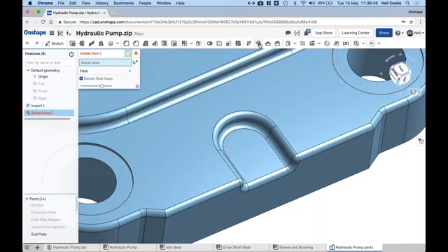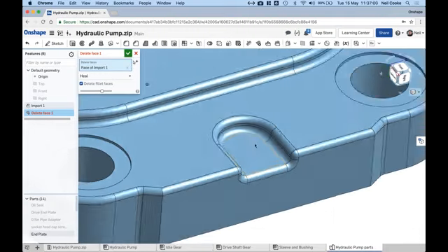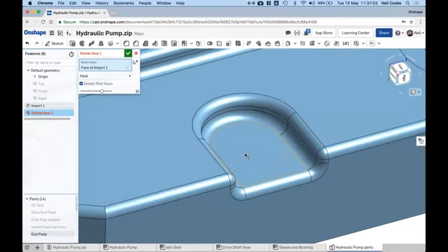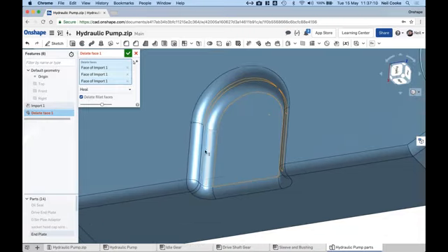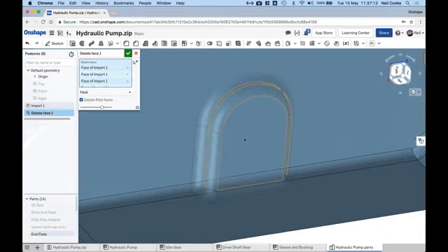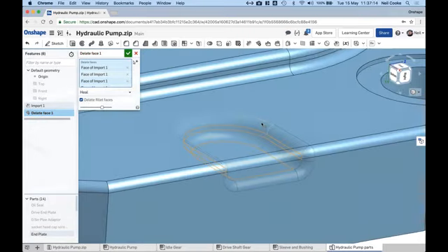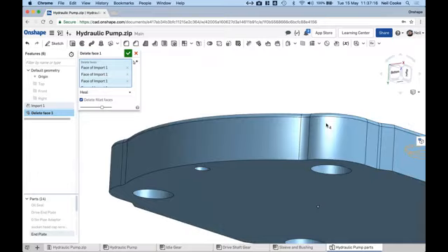So there are 4, but out of those 4, there's some very powerful things you can do. For example, delete face, one of my personal favorites. So if you've got something like a feature, it could be as simple as a hole, or it could be an indented boss like this, you can delete faces and just get rid of that feature entirely. Now, you don't have to pick everything. You just really need to pick the geometry which makes up the face, because the fillets really are neither here nor there. So you'll see from the preview that feature is gone entirely.